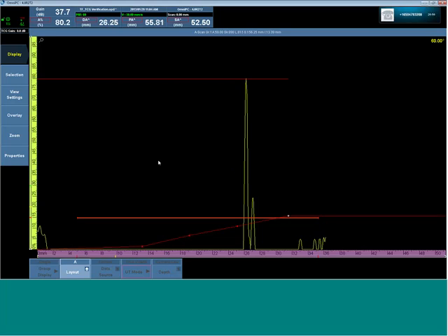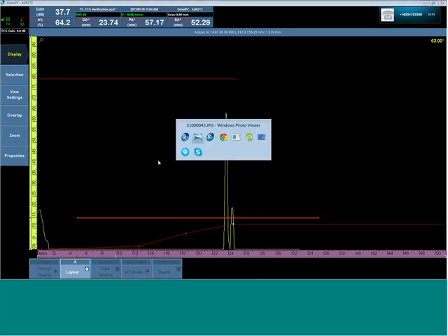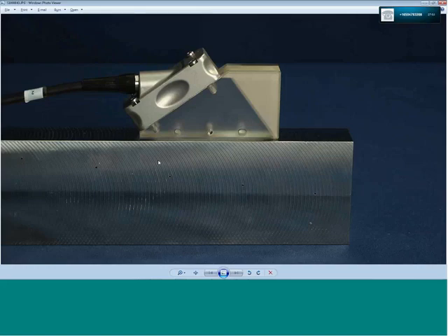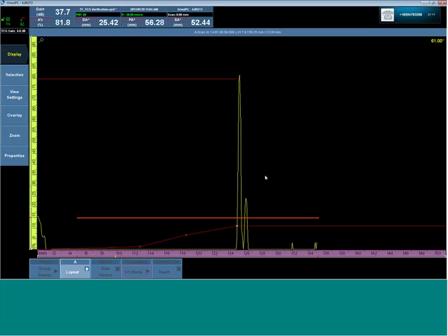We can see right away from one single phased array probe, like we're seeing here, looking at a regular calibration block, we can change the angle, the beam shape, the focal point, and many parameters of this A-scan that were previously related to hardware.